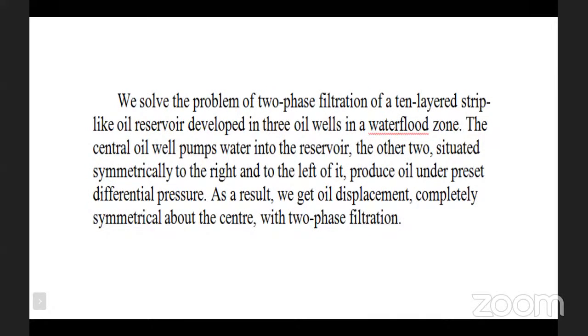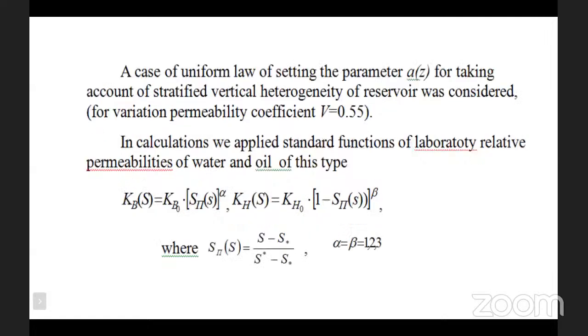We solved the problem of two-phase filtration of a 10-layered strip-like oil reservoir developed in 3 oil wells in a water flood zone. The central oil well pumps water into the reservoir. The other 2, situated symmetrically to the right and to the left of it, produce oil under preset differential pressure. As a result, we get oil displacement completely symmetrical about the center with two-phase filtration.